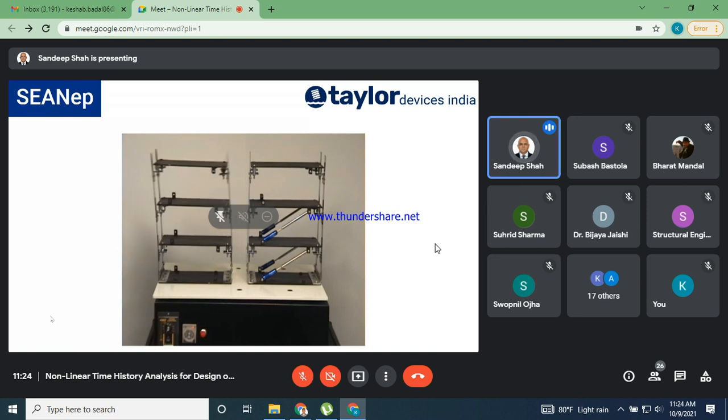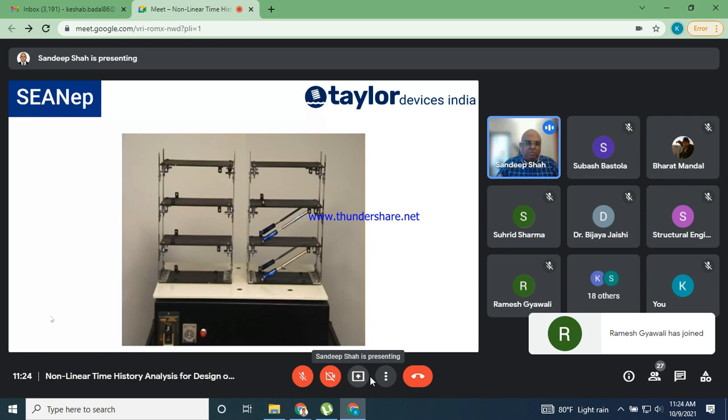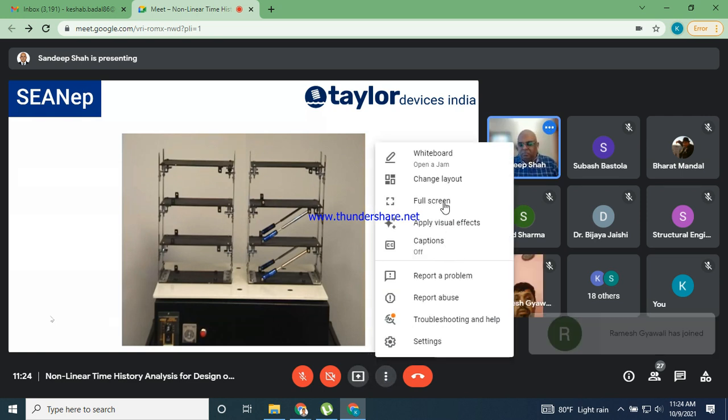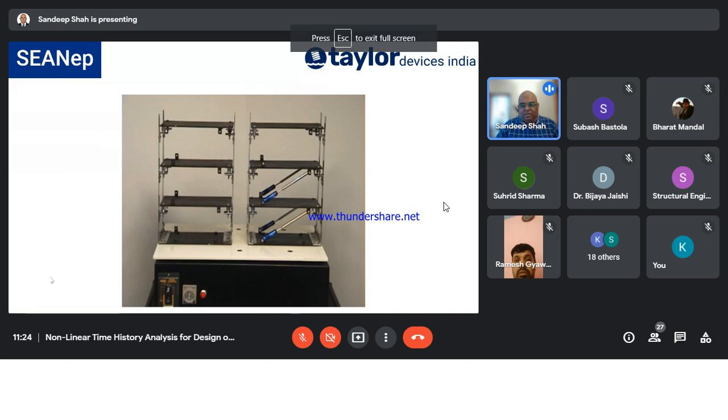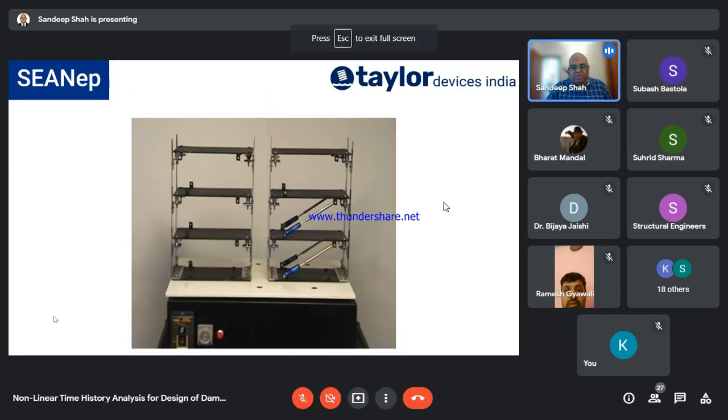So, this video is primarily to demonstrate two things. Firstly, both are flexible buildings. So, dampers do not add any stiffness to the building. The building remains as flexible as a building without dampers. But what happens the moment there is lateral shaking, the moment the earth shakes and the building wants to move, the dampers absorb that seismic energy, and we're going to speak a lot about the energy component, earthquakes and how the building behaves in this energy component.